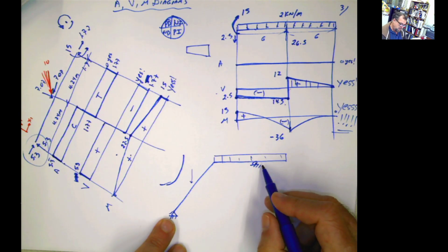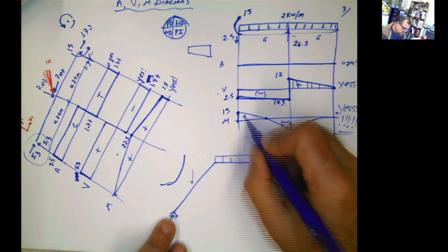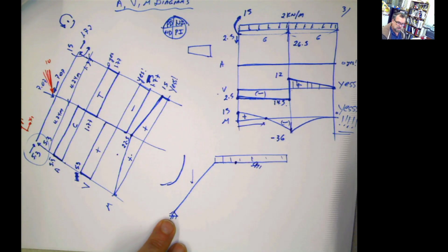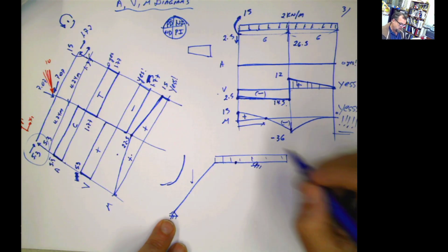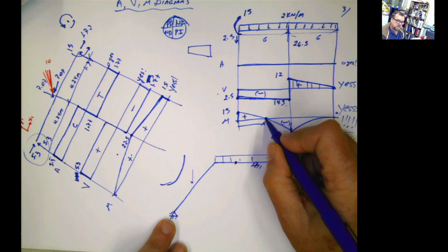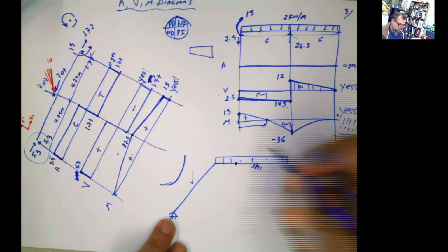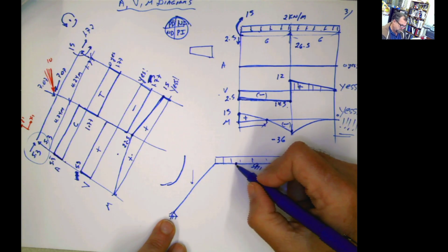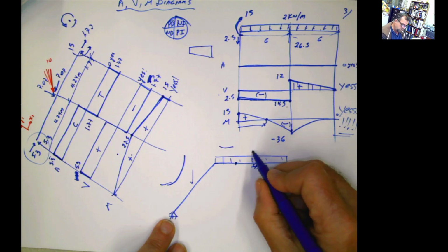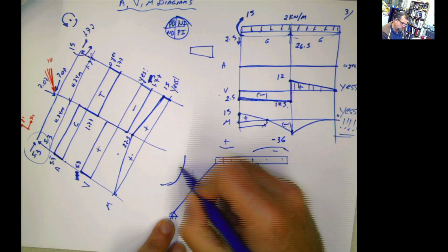And for this other area, if you look at this closely, this part is going to be positive up to that point. By the way, you can calculate that if you have the equation of this moment. And you have an inflection point there. Whenever the moment is zero, then you have an inflection point in the deformation, in the shape of this curve. This is positive in this part, and the whole diagram from this part is going to be negative. The moment is going to be like that: positive, negative, positive.